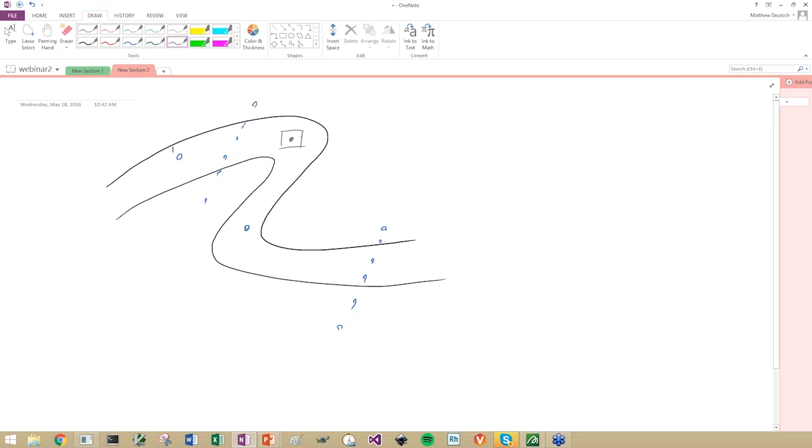The first step of bend unfolding is that this location, this block, is now going to become the center of our world. This is our new center in the new x and y coordinates. Its z coordinate will be similar to projection: any point along the bottom will have a new z coordinate of 0, and anything along the top would have a z coordinate of 1 in our new space. But we're going to determine new relative x and y coordinates for every point by walking along our surface.